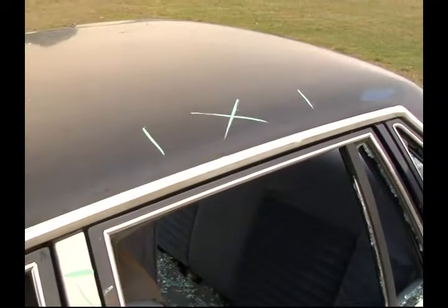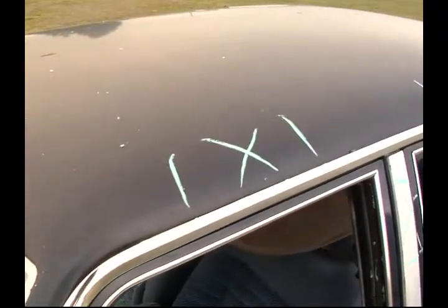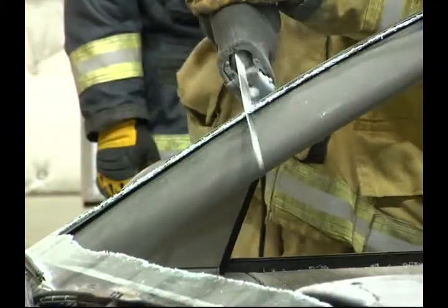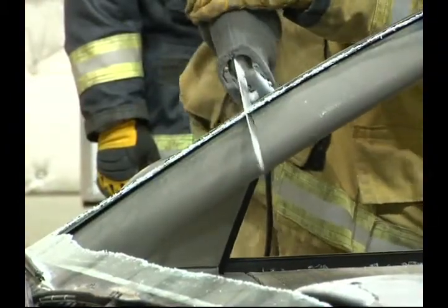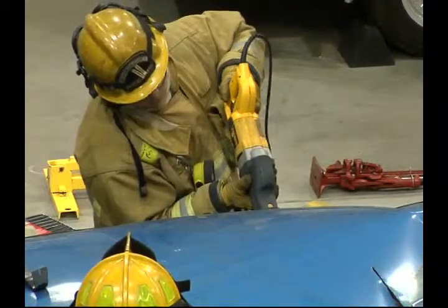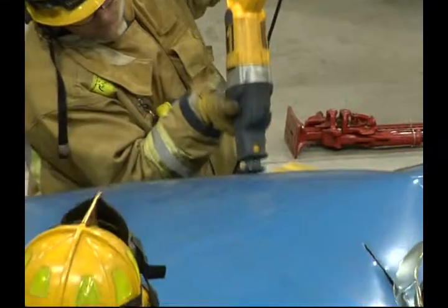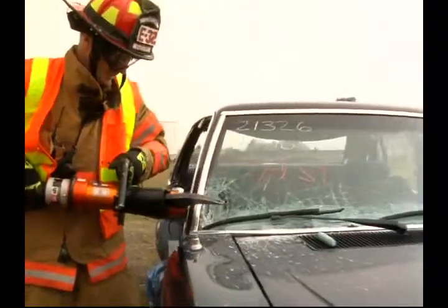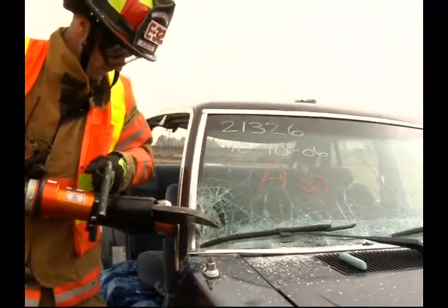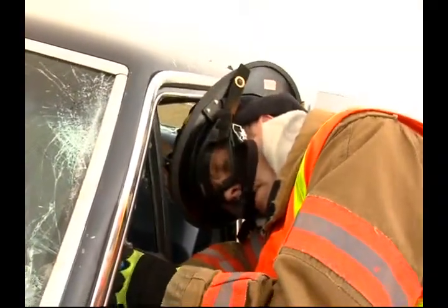Now that the hazard has been identified, you can begin the cutting required for a roof flap. In this evolution, you will peel back the roof by cutting through the 2 front A-pillars, as well as making 2 relief cuts toward the rear at the roof line in front of the last pillar. You can accomplish this with any kind of cutting tool. Peel away the trim and make note of any airbags you need to avoid.